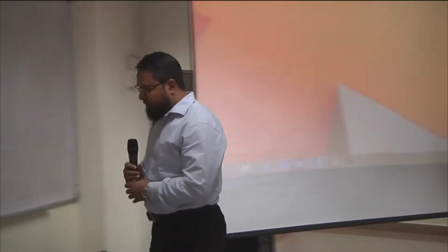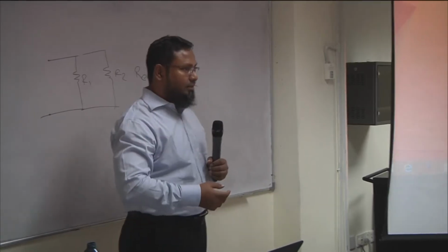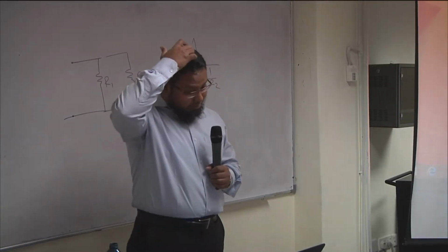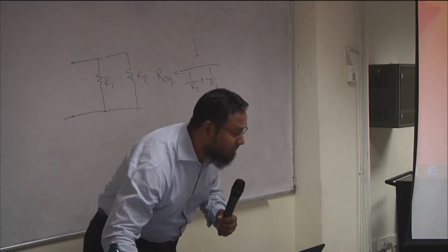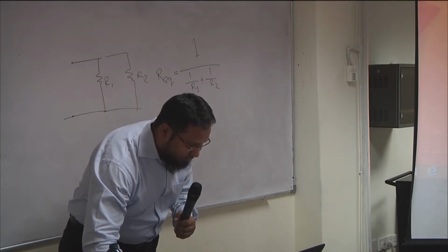My name is Afiq Amirullah. The current through a capacitor is equal to the rate of change of the voltage across it multiplied by the capacitance value, or in other words, i(t) is equal to C dv/dt. So it's proportional to the rate of change of voltage, and the result is that the current leads the voltage across it by 90 degrees. That's great. Afiq, thank you very much.